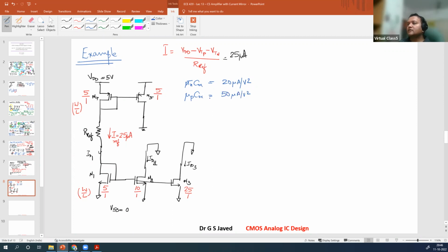Is this correct? No, this is inverse, because we said the mobility of the PMOS is lesser than the mobility of the NMOS. So if you see, this is flipped. So remember, whenever you see in your data that the mobility is inverted, always clarify. Here, in this particular case, the ratio that you are getting is mu n equal to 2.5 times mu p. Right?